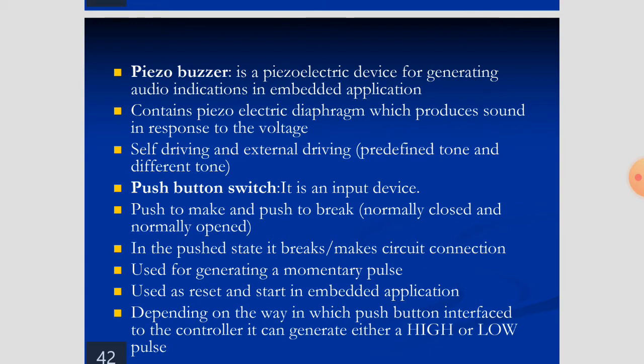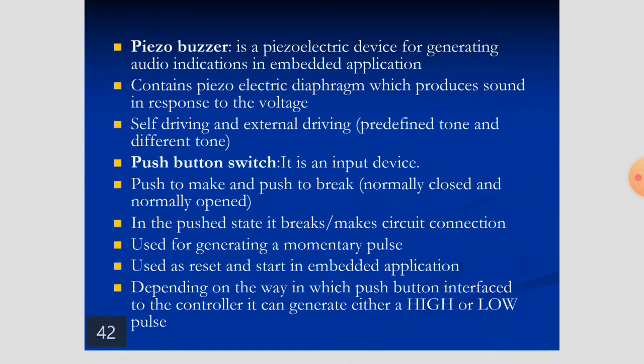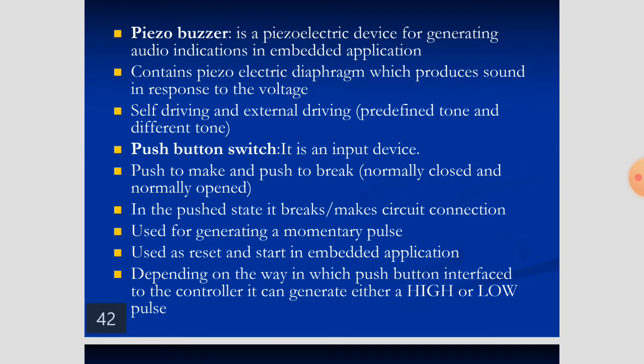In embedded systems, they are used to generate different tones. A piezo buzzer mainly contains a piezoelectric diaphragm, which produces sound in response to voltage. According to the level of the voltage, different voltages on the diaphragm generate different levels of tones.